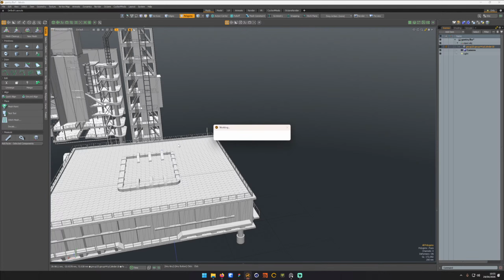So the reason why I've gone to Modo instead of Cinema 4D is mostly because modelling in Cinema 4D is actually pretty awful. Although, if I were to do this sort of thing, let's say to get this tower, you'd have one instance of a floor, or a couple of instances of a floor, you'd then replicate them on top of each other, stack them up, and then add some variation between those instances, so you'd either bake it down or stage some stuff on top of it. So we could do that in C4D actually, because this sort of thing is pretty straightforward. When you're doing real modelling, like changing actual geometry, that's where Modo kind of shines.